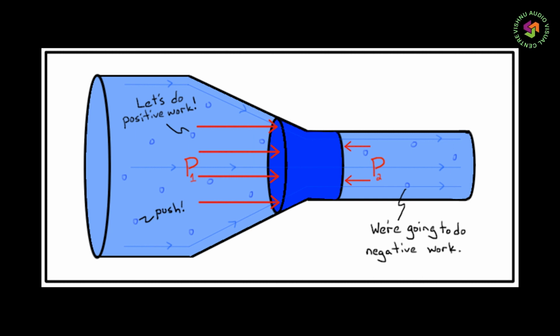Right. Next, third point. The question may be, what is the loss of head between the two sections? When the question is the loss of head between the two sections, calculate the total energy at section 1, calculate the total energy at section 2, then see which is higher, and then higher minus lower is nothing but the loss of head.